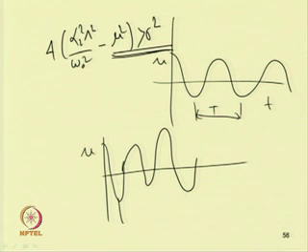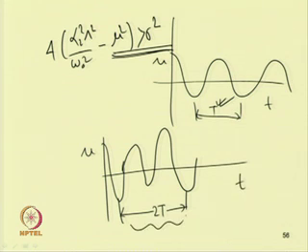Okay. So, this to this, now this is one period of the system. So, this period is 2 t, unlike here where the period is t. So, when one considers the subharmonic condition, the time response becomes 2 t. In this case one can see the free oscillation adjusts itself to that of the external excitation, which is nearly equal to twice omega 0 of the system.